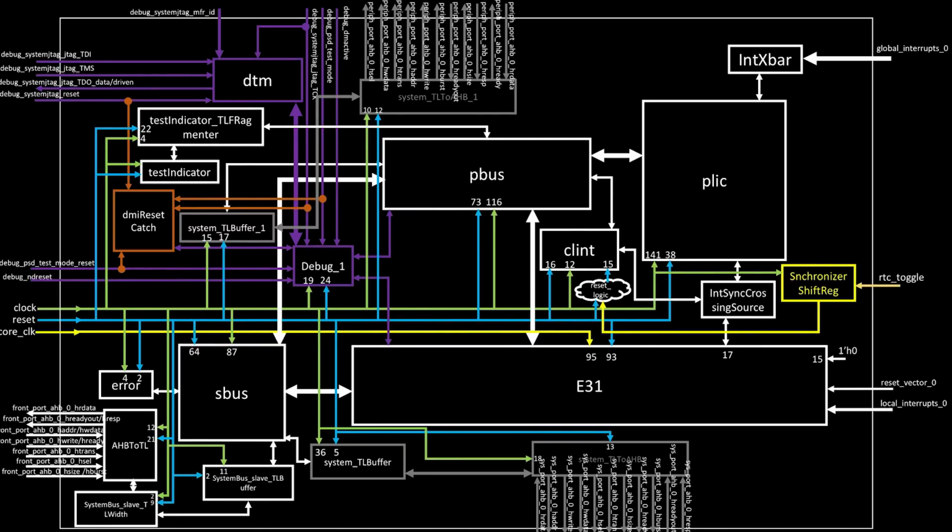If you see over here, this is not a regular block diagram which comes out of the specification sheet. It's basically a floor plan. So physically, this block, let's say P bus, will sit exactly over here on a chip. Physically, these pins will be sitting at these locations in order to get the optimum speed or the highest performance that you expect from a high-speed CPU. Physically, the clock reset and the core clock have to come over here so that they can create a proper H tree.